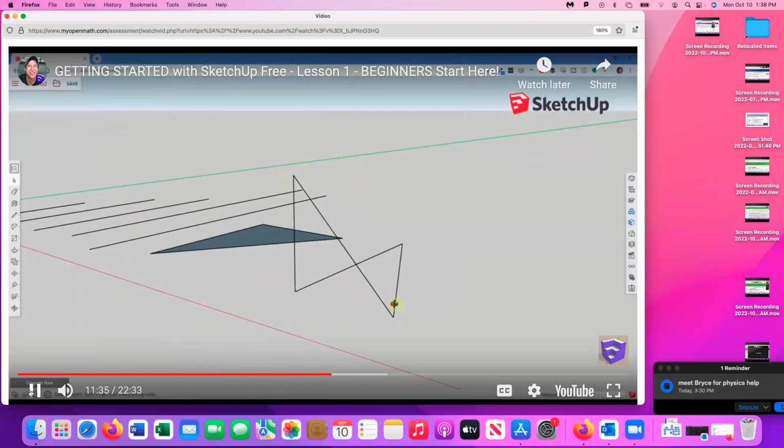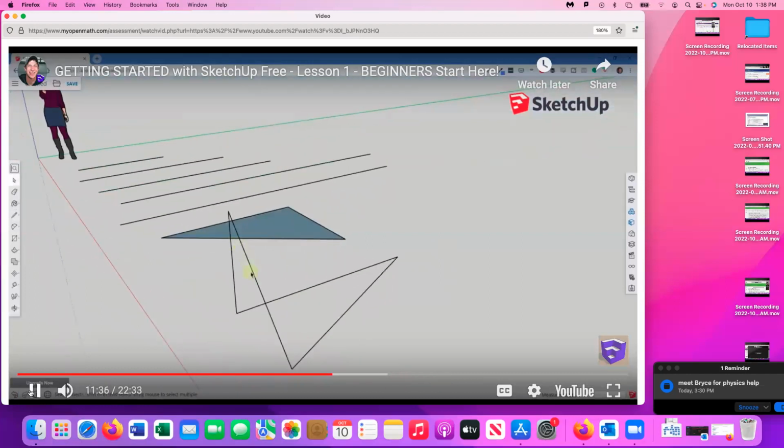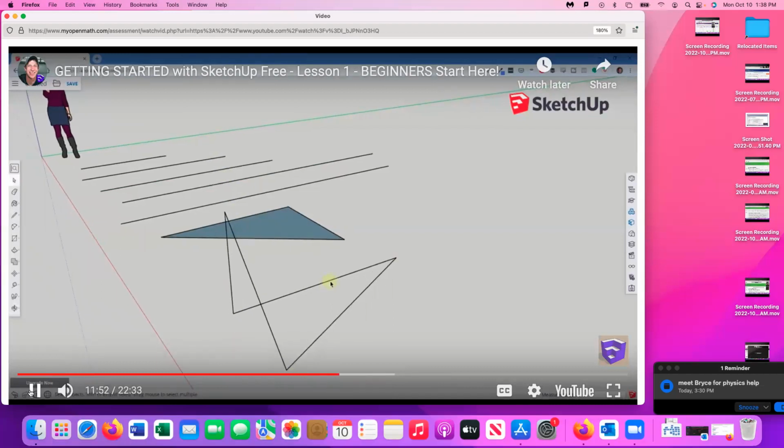doesn't actually fill in a face, because even though I have 4 edges in here, they're not on the same plane, meaning this edge and this edge are on the blue plane or the flat plane, and this edge is on the red plane, which is a vertical plane. But you can see how SketchUp isn't filling in a face because this doesn't have 3 or more coplanar edges.